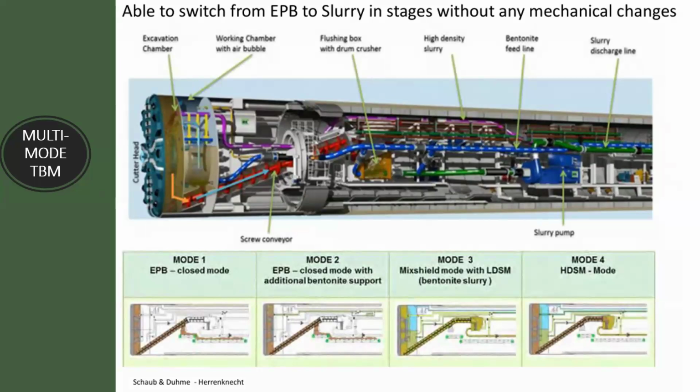Now, there will be a minimum number of segments when the initial drive will be finished and the TBM is capable of taking the thrust of the segments. So the designer makes a calculation of how many segments I have to install so that the TBM can put my desired thrust on the segments.